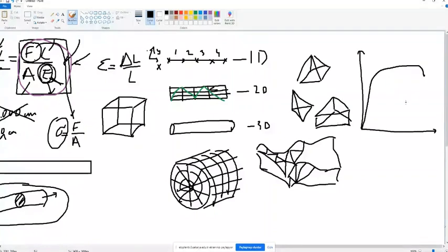But when you look at my first example, the guy went to the measuring area for a truck. It is measuring a huge range. So you need to know what will be the reaction force of your sample. Approximately, you have to know it. You have to buy that type of load cell.